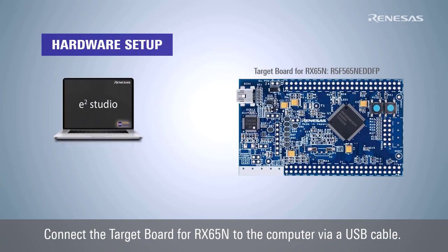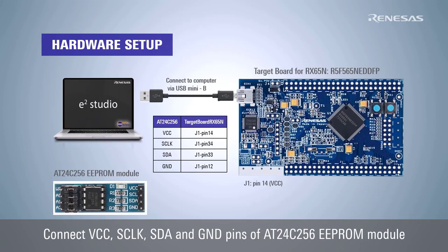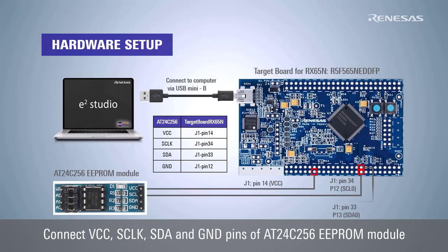Connect the target board for RX65N to the computer via a USB cable. Connect VCC, SCLK, SDA, and ground pins of the AT24C256 EEPROM module to the target board.